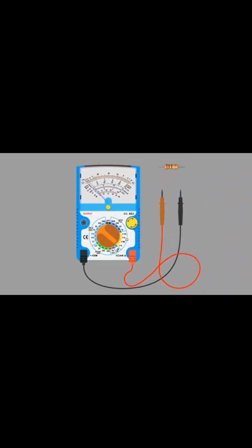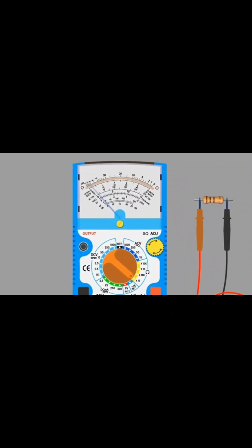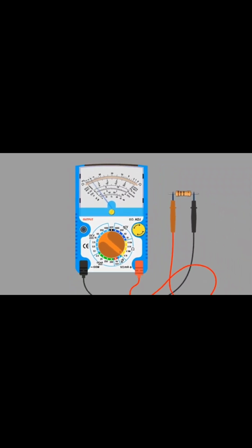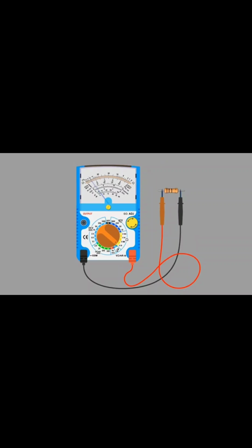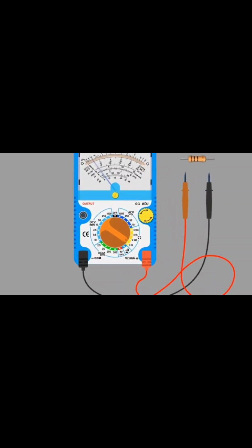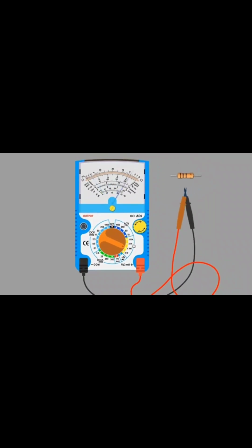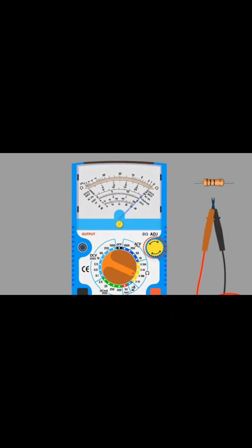Take a resistor whose value we need to measure. Connect the probes to the resistor. If you find no movement or little deflection in the needle, it means our selected range is too low and the resistor has a greater value. Disconnect the resistor. Now, I am selecting the X100 range. Short both probes again in order to calibrate it. Rotate the ohmic knob clockwise or anti-clockwise in order to adjust the needle at the 0 scale. Disconnect the probes.